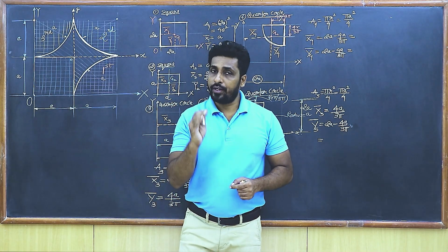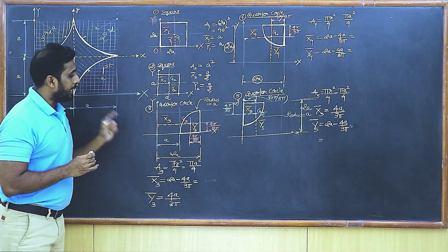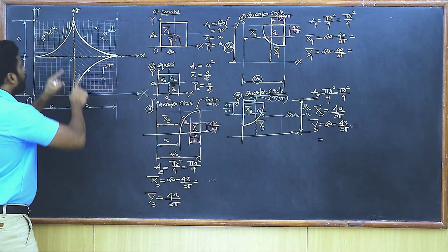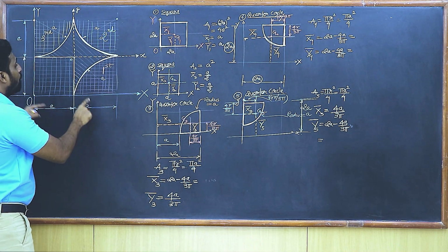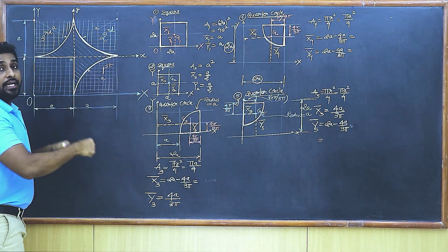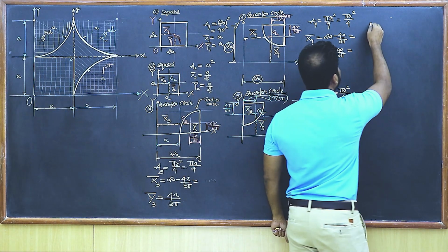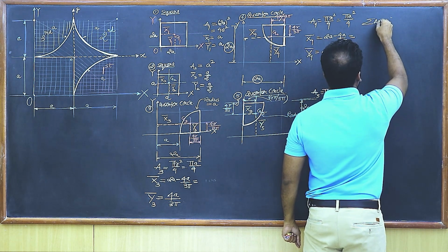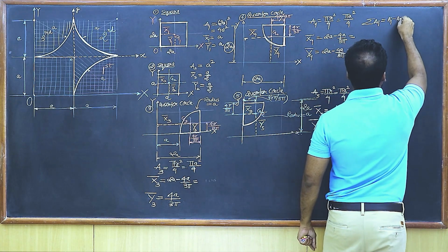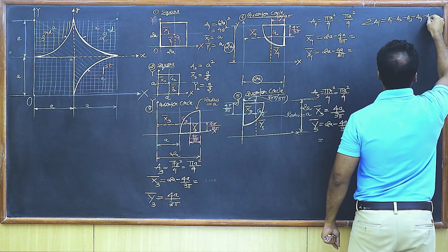So I'm going to write the value of a as a1 minus a2 minus a3 minus a4 and minus a5, because I know from the very big square I want to remove the smaller square and the 3/4 circles. That means all the areas are going to be negative except a1. So I can write here summation of ai. Let's get summation of ai here. So summation of ai is going to be a1 minus a2 minus a3 minus a4 and minus a5.